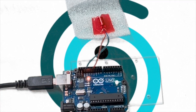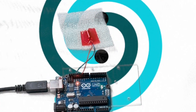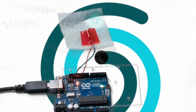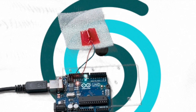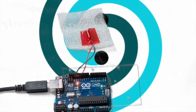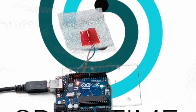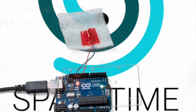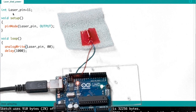This is our hardware setup where you have the Arduino board already connected through the USB cable to my laptop. We have connected the laser diode's positive to pin number 11 and the negative to the ground, which is close by. This is the advantage of having several grounds. You can easily use them to connect an external circuit. Now we flash our code. The code is basically here. You have laser pin 11 as our output, and we use the maximum power, that is 255 in the analogWrite. So that would be a 100% duty cycle.